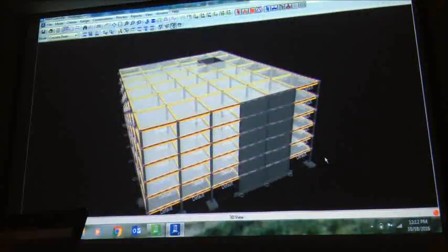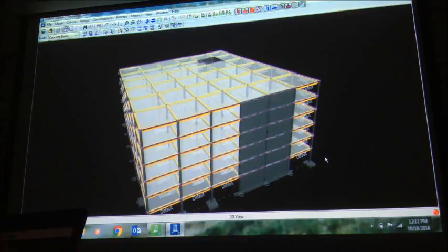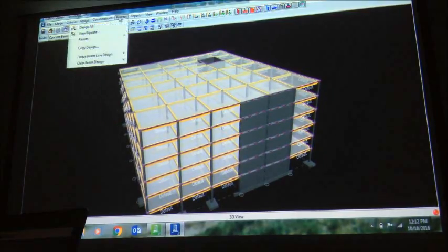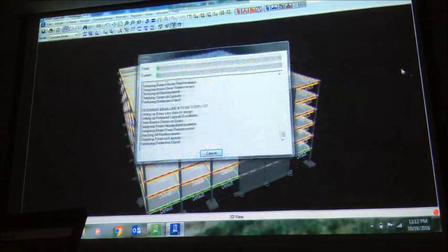Yes, Becky. I have one question. For designing beams and columns, do we need to include seismic load combination into our design? Yes, these are gravity designs now. When you are doing the say shear walls or moment frames, you need to have a seismic load combination. That's I'm going to show you in about if I have the time. Okay, thank you. Okay, let's go design off.